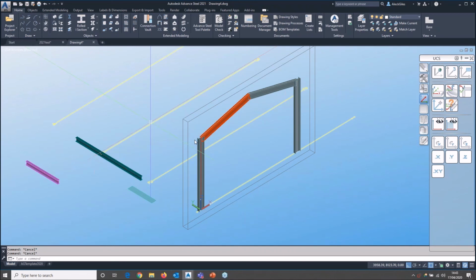With previous versions, when double-clicking on a fabrication dimension, you could roll your mouse wheel and edit the dimension. In 2020, this doesn't work anymore. Not sure what you're editing, Matthew. If you want to change the type of dimension from absolute to relative and absolute, or to relative or whatever, it might work if you just clicked once on that list, so that list has the current focus, and then roll the mouse wheel. But if it's changed, it's changed. There's nothing I can do about that. I've never tried doing it the old way, I'm afraid.